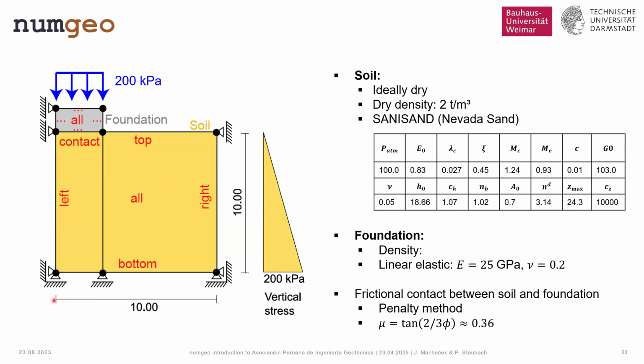So the sand domain has just 10 meters width and 10 meters height. And then we have a foundation with a width of 1 meter and a height of 0.5 meters. Now we will load the foundation with an external load, a surcharge of 200 kilopascal. So that will be the problem that we will simulate.